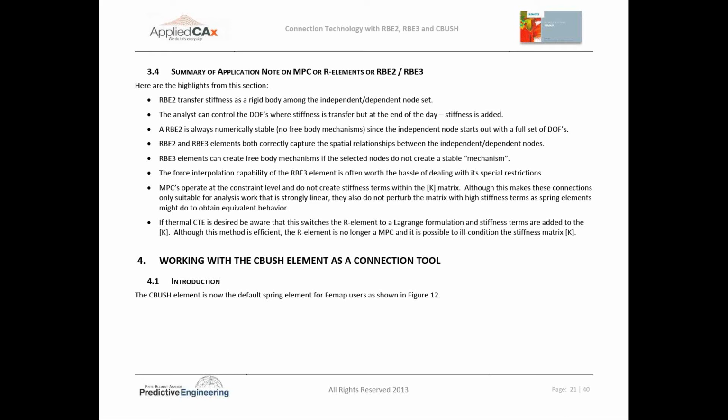And interpolating stresses around it can be tricky. That's why it's useful to understand what it's doing. It helps you interpret the stresses that you're seeing, and whether they're truly an artifact of the R element over-constraining the material, or whether they're real. I mean, how do you discount stresses around an R element if you don't really understand what it's doing? So hopefully this little theoretical background will provide that.